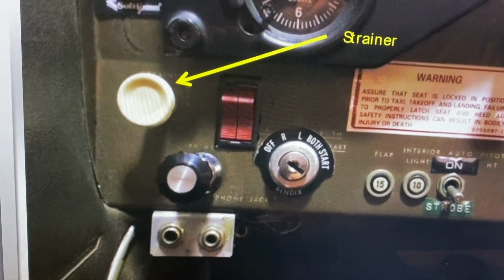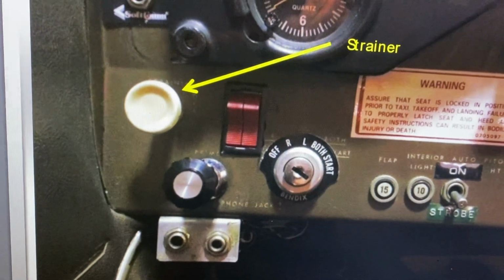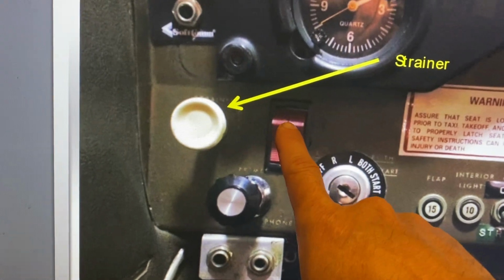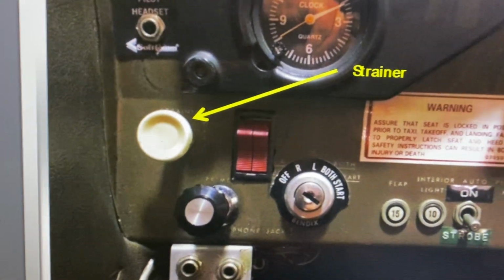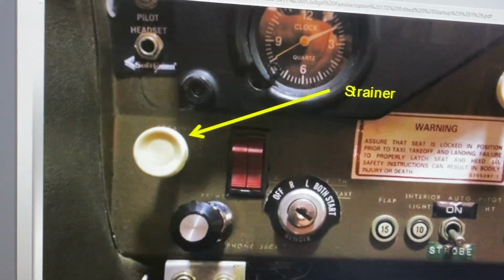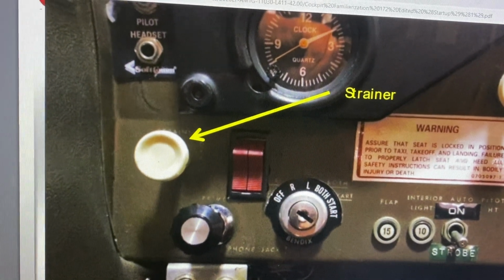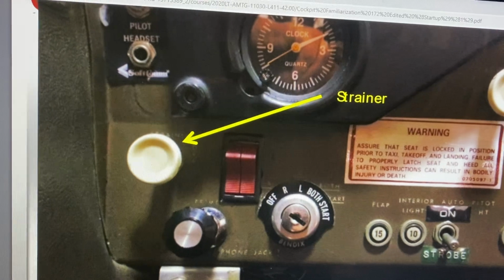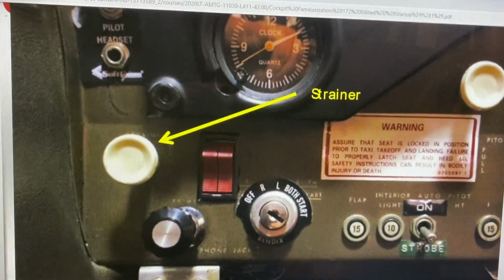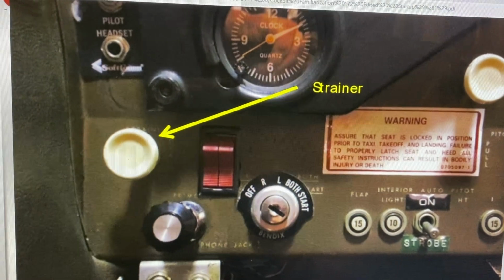And then once you yell clear prop, you're going to turn your master switch on. So that's where you're going to hit this switch on. The master switch, again, the electrical power switch, you're going to push both those halves up and turn the master switch on. Once the master switch is on, that's when you'll hear everything kind of start to purr. Everything comes online. Any lights that are on come on. The radios come on. Everything comes on with that switch.